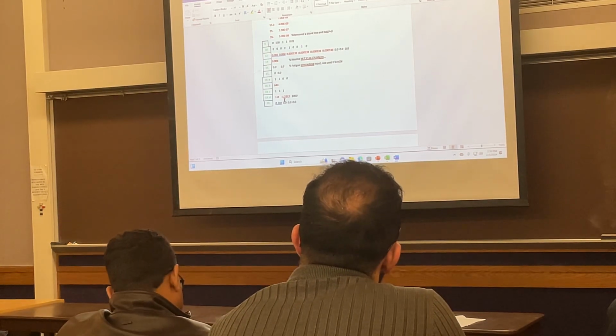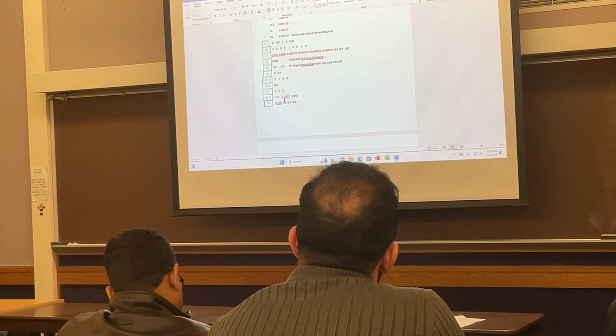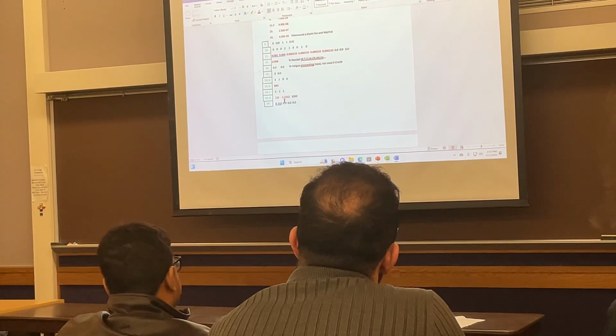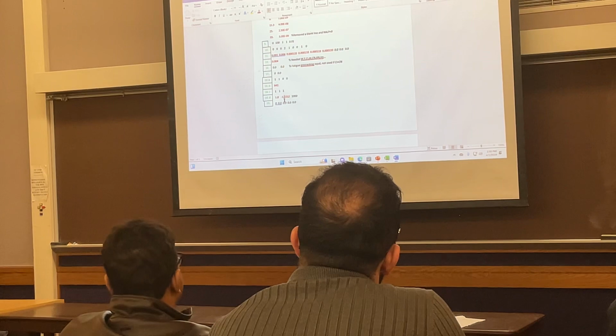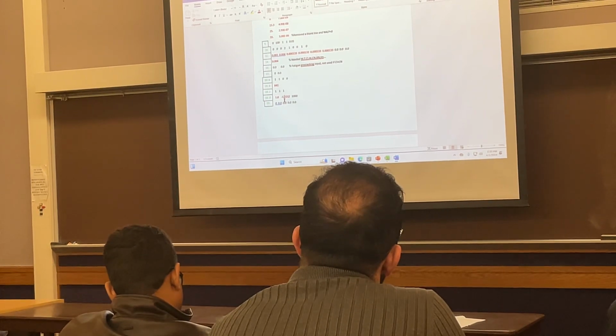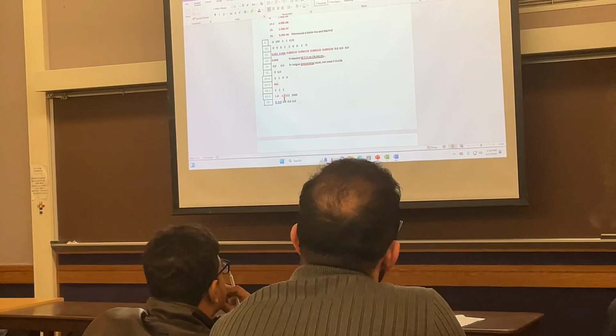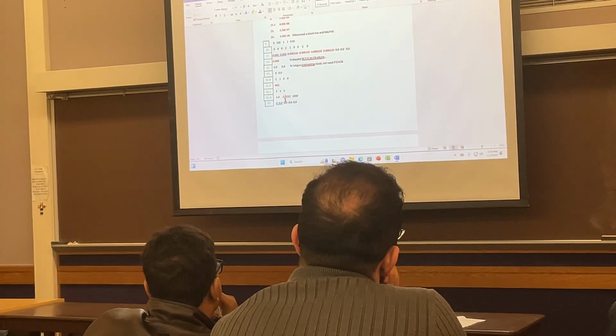Here is megapascal. Instead of giving minimum stress as a value, it's just the R ratio. So what you see is minus 0.12, which is basically the R ratio that you have. So if you multiply this with this one, you get the minimum stress. That's the way that you put maximum and minimum.